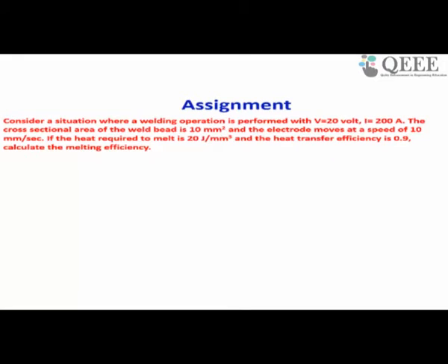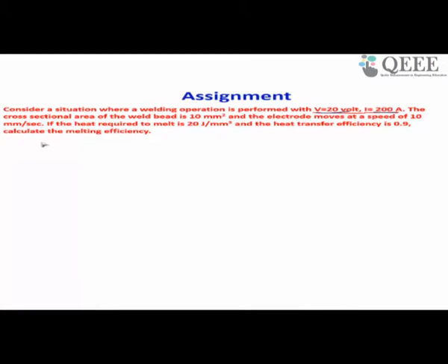So what is the answer? Anybody done? Please solve it. Here voltage is given, current is given, and the transfer efficiency is given. So transfer efficiency equals what? Net heat supplied by total power heat input, isn't it? So what is the net heat supplied?